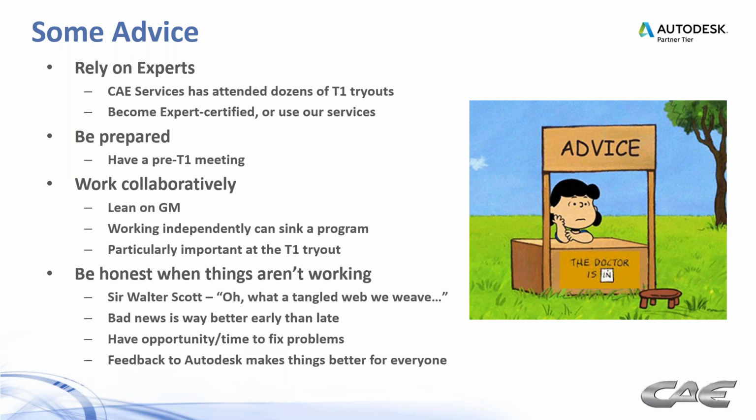And then lastly, feedback to Autodesk makes things better for everyone. There are a lot of things going on with Autodesk R&D right now that relate to the T1 tryout process. Appearance issues, there are a lot of things that Moldflow traditionally hasn't been able to identify as far as appearance is concerned. For example, tiger stripe. That's one of the things that Autodesk is working on.